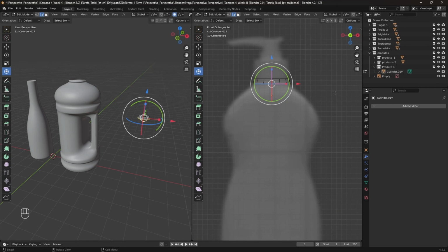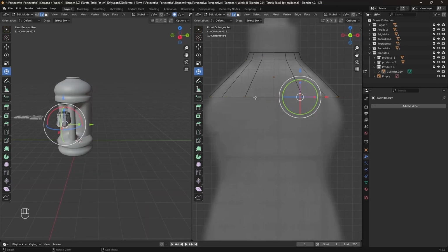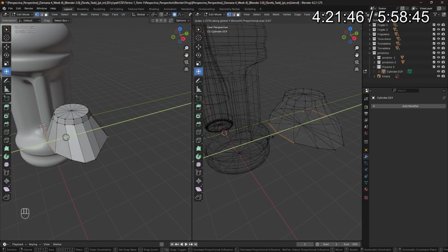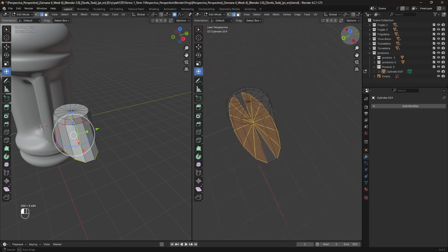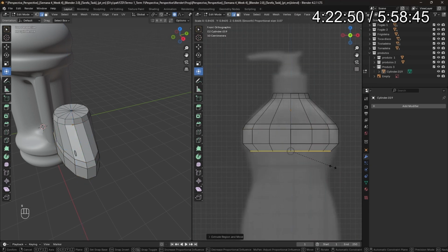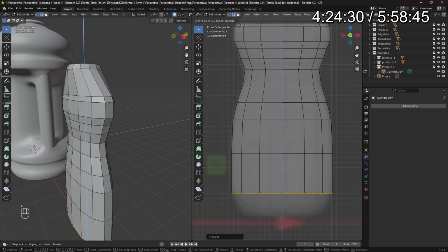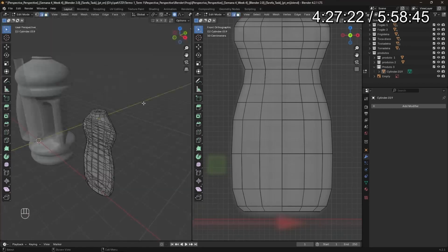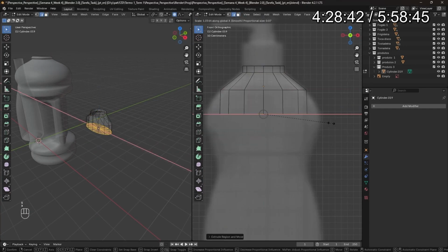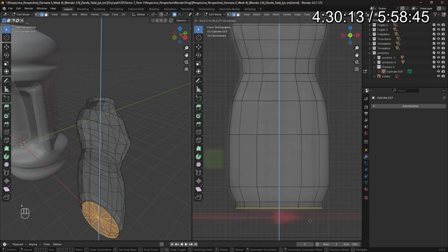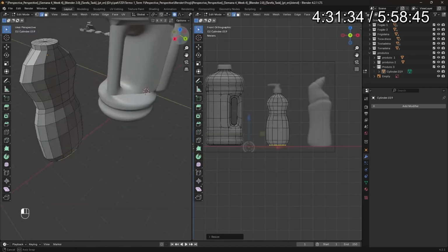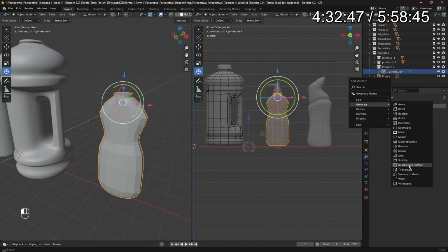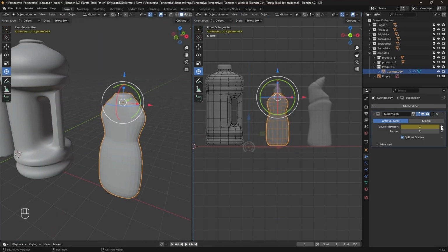Over here the idea was to scale this on a specific axis. You can see that I was just scaling on the x-axis. So it's making an extrude and then scaling on x. You extrude on the z-axis and then scale on the x-axis, like I explained in the introduction part. Here I was facing problems, so I decided to redo it properly to achieve the result that I wanted. After that I went to the bottom part, added the details, and also applied the subdivision surface modifier.